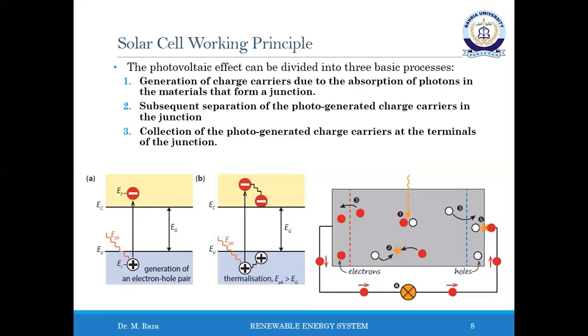If one wants to use the energy stored in the electron-hole pair for performing work in an external circuit, semi-permeable membranes must be present on both sides of the absorber, such that electrons can only flow out through one membrane and holes can only flow out through the other membrane. In most solar cells, these membranes are formed by N and P type materials.